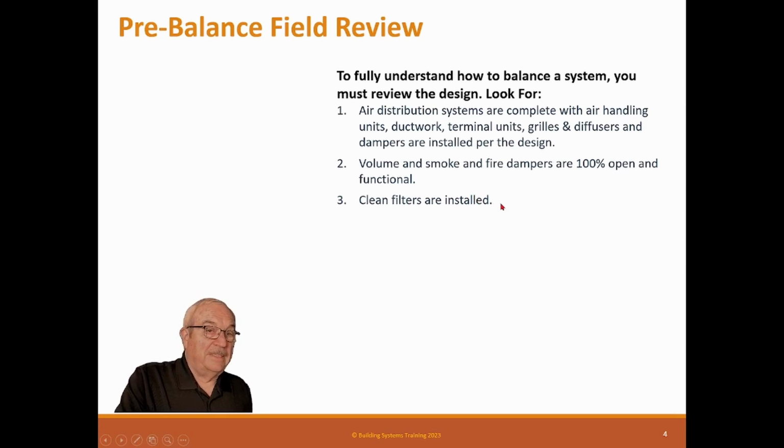Sometimes the specifications call for you to balance a job with a certain pressure drop across the filters. They're trying to simulate dirty filters instead of clean filters. Normally my advice, and of everything I talk about, is make sure we have clean filters before we balance so we can get maximum flow to do the balance. And if you have to simulate dirty filters, what you have to do is put pieces of cardboard in some of the filters to act like a dirty filter so we increase the pressure. You can do that, but it's really best to do clean filters so you can get maximum flow, especially on systems that are somewhat limited.